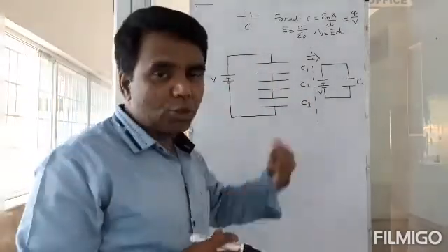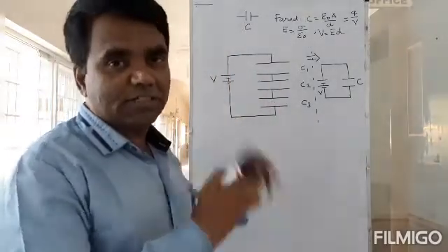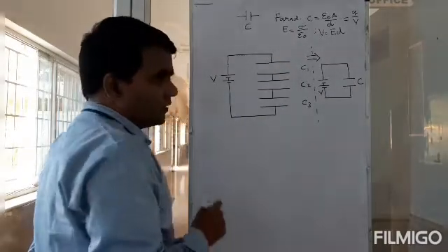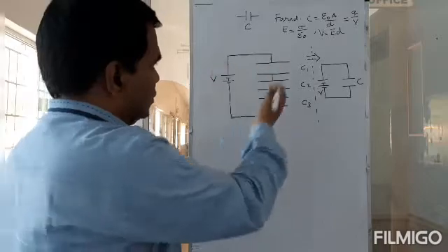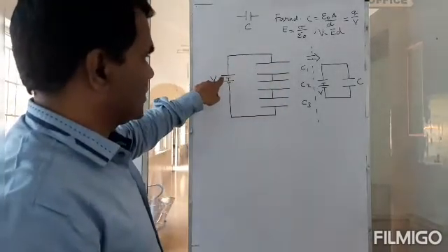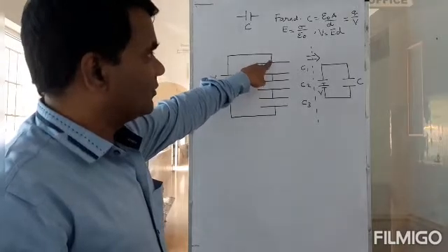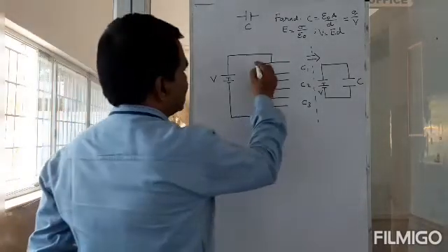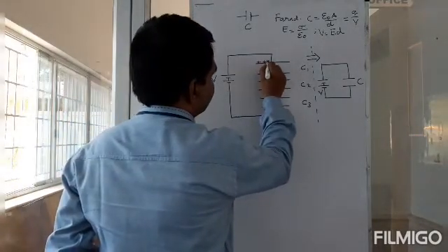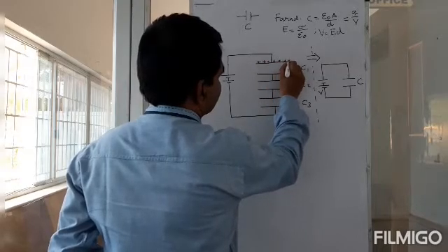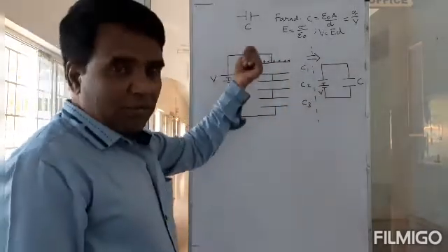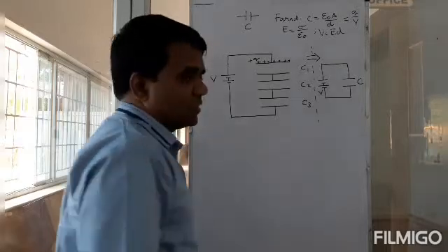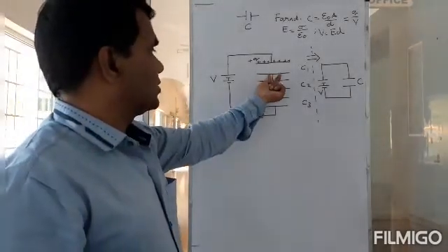Having stated this goal, let us focus on what is going to happen here. I have connected the positive terminal to this plate of the capacitor. This is a metal, so the free electrons will run through this to the battery, leaving this plate net positive. Because you have net positive there, let's say this is plus Q.